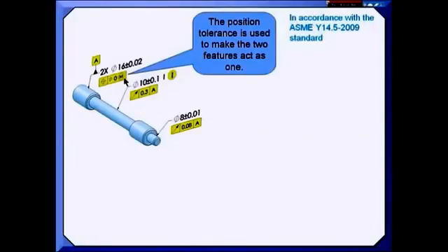Because I'm using zero at maximum material condition, there is a boundary at perfect form, the virtual size, in other words, at 16.02.